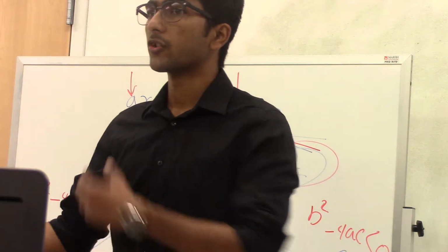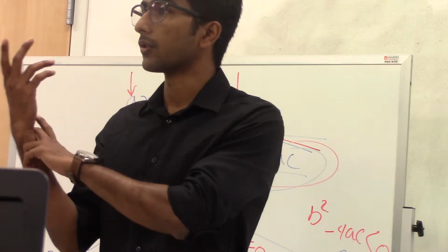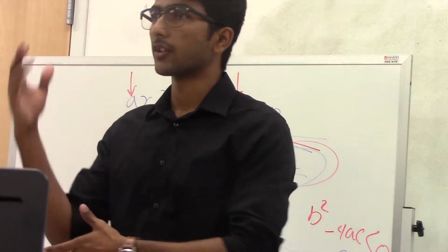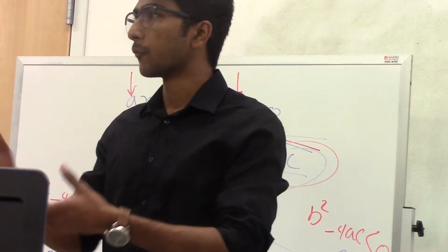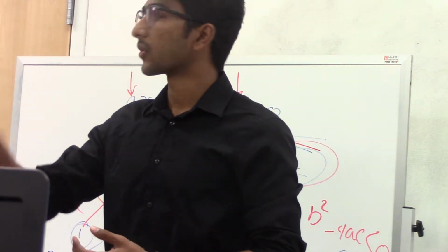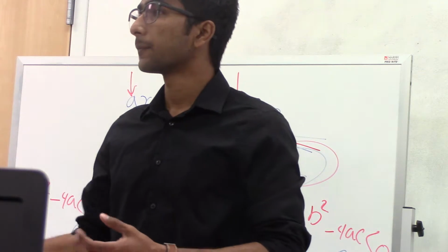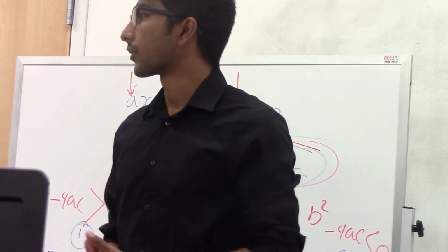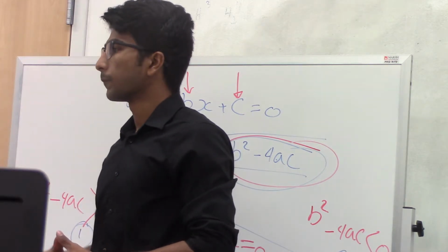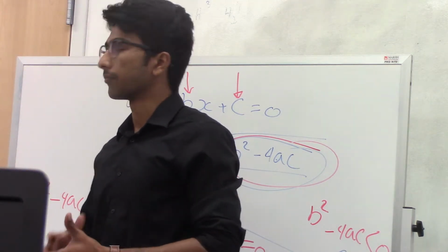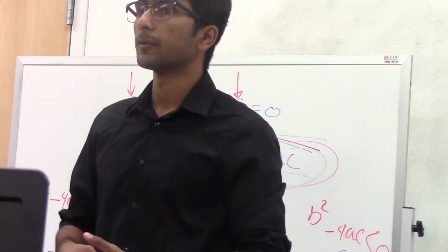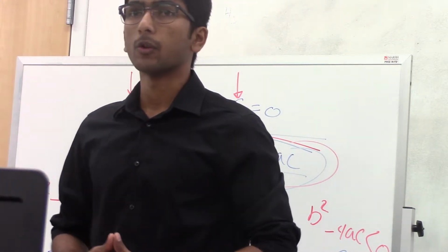So imagine your arm. How many joints do we have here? 1, 2, 3, 4, right? If I turn my first joint to a certain angle and the second joint to a certain angle, and the same with the third and fourth, we should be able to calculate the end effector position in three-dimensional space. This is forward kinematics: given the joints, we calculate the XYZ of the end effector. Inverse kinematics is the opposite: given the XYZ, we calculate the angles of each and every joint of the robotic arm.